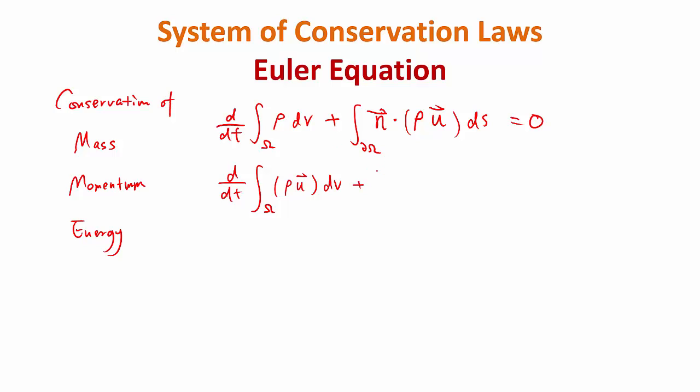Now the tricky part is, what is the inflow of momentum? What is the outflow of momentum? It's n dot what? Yeah, rho u times u. And here I'm just going to write the product. It's kind of a tensor product. It's tricky because this equation is actually in 2D. It's actually two equations. And we also have two fluxes, an x and y flux.